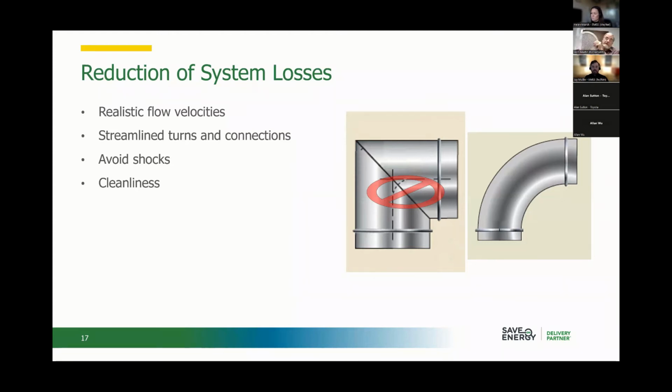But I'll tell you, the pressure drop across an expanded metal screen is not good. Okay. And if you have that and you want to replace that with something like this and still put a wire mesh across there, you're going to see a significant pressure reduction as a result of doing that.